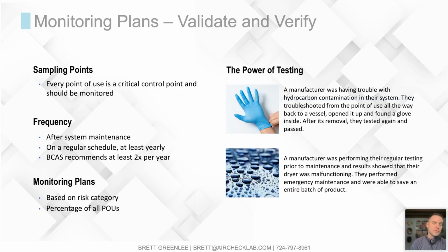Another microorganism win that we've had in the past, that I thought was in this slide but is not, was when we were getting alert levels of microorganisms in a compressed air system for a customer. We were able to help them troubleshoot and identify that pigeon feces were the cause of the contamination at the intake side of the compressor system. They were able to mitigate that issue moving forward, get passing results, and protect their product and their consumers.